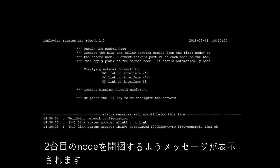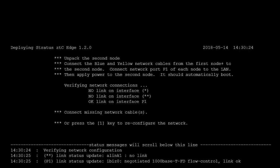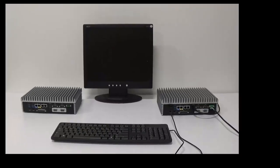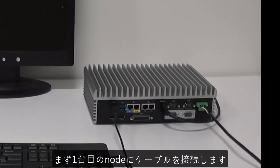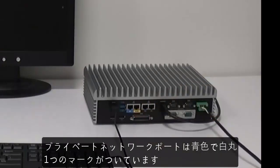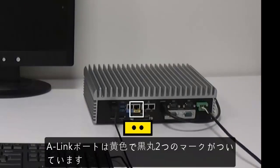A message to unpack the second node appears. Follow the messages on the screen, which also instruct you to connect the blue and yellow network cables and to power on the second node. We'll first connect the cables to the first node. Notice the ports on the ztC Edge node are clearly labeled. The private network port is blue in color and has a single white dot. The A-Link port is yellow in color and identified with 2 black dots.